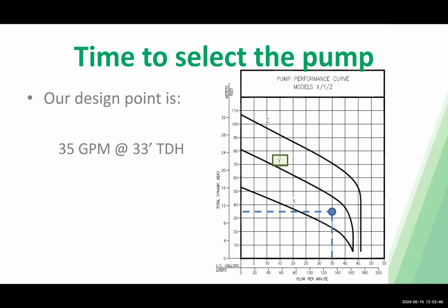In some pumps, yes, we've spec'd out a couple for sump pumps. You mainly want to use VFDs in sump pump applications when you have an area that gets highly variable levels of rain, so maybe you want to keep that pit consistently dry. Sometimes it may rain a significantly lesser amount than at other times, so you can use a VFD to fluctuate when that happens. But they are available. That is something that we've done before.